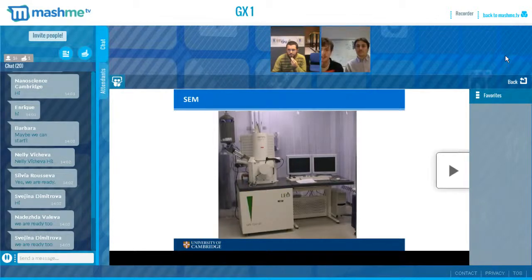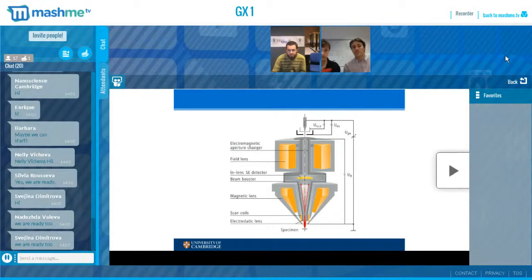You need it to be inside a vacuum chamber so that the electron beam doesn't get scattered or blocked by air. So it has to be under vacuum. The electronics controlling it all are housed in the big box underneath that chamber. On top of the chamber, you have the electron gun, which accelerates the electrons and focuses them into a beam that you can use for imaging. And off to the left, there's an X-ray detector, so you can detect X-rays that might be given off by the samples during imaging.